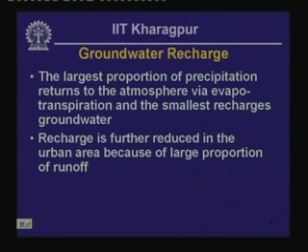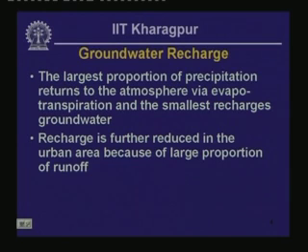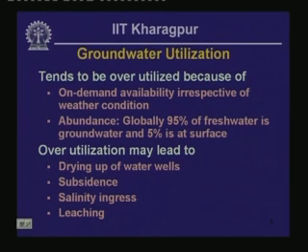And you should also note that recharge in the urban areas is further reduced because of the existence of built up areas, from which the precipitation that is received runs off to the nearest stream and exits the area as surface runoff. So you have to be very judicious when you are planning to utilize a groundwater resource in a certain area.